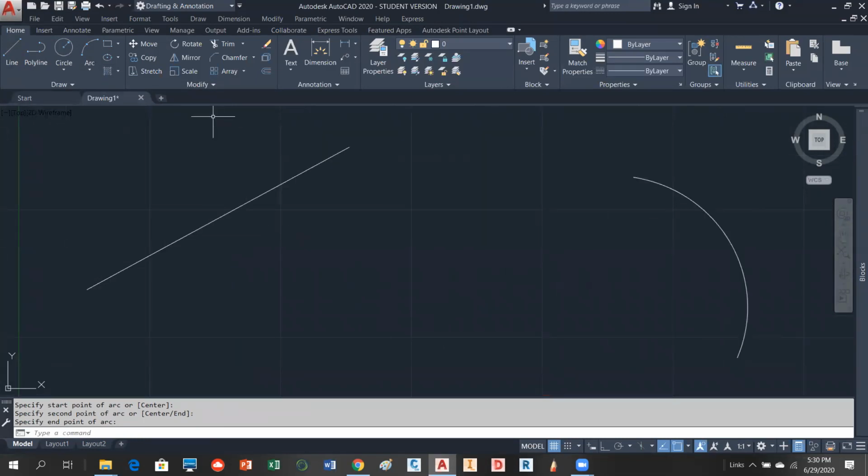So we're going to go into the lengthen command. And it should give you sub options, okay? First of all, it's saying to select an object, but right now we haven't done anything, so we need to know what we're doing. So first thing we have is what's called delta. Then you have percentage or percent, total, and dynamic. So you have 4 different options.